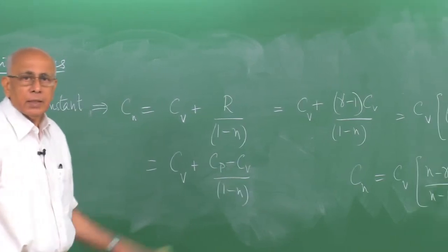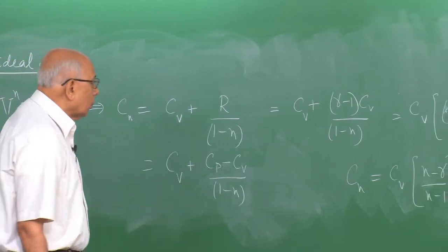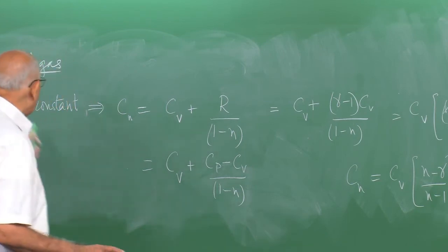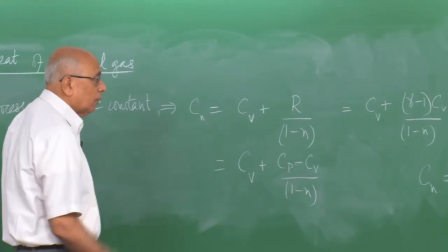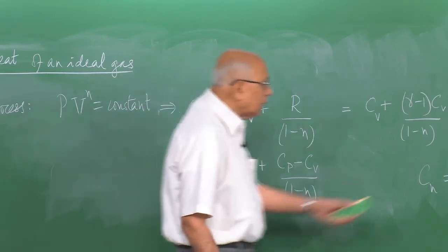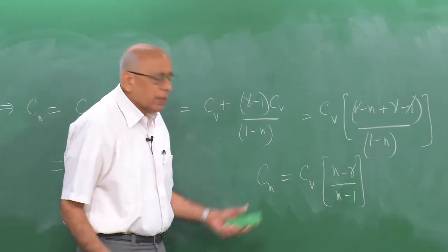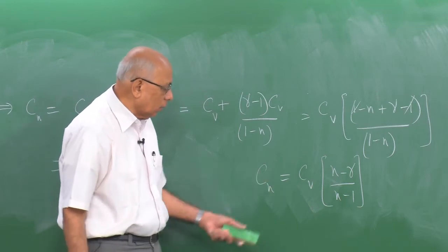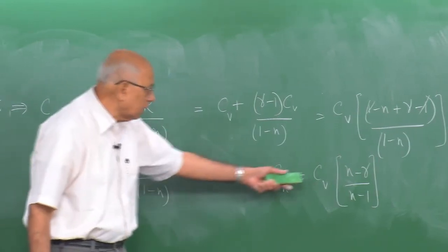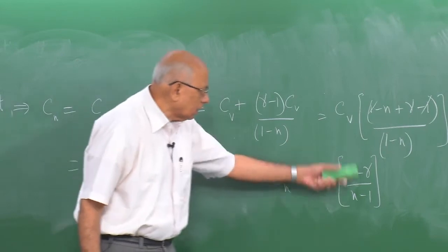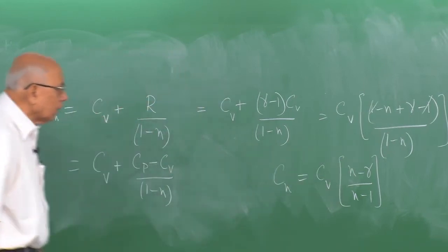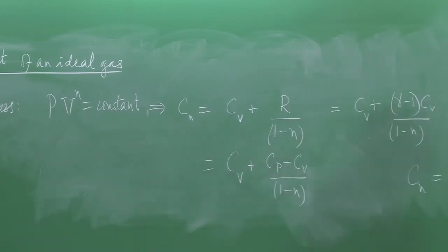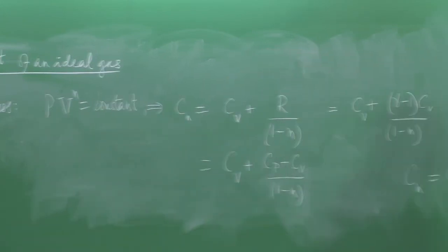And that is it, that is the general answer here. So we have an expression for the specific heat for a general polytropic process for an ideal gas, 1 mole of an ideal gas, which is Cv times something or the other. Now physical dimensions imply that this thing must also have the same dimensions as dq over dT, energy over temperature, which is what Cv has. So this is a dimensionless ratio here, and that is the general formula, and it tells us that all the special cases should emerge automatically, and let us see if that happens.